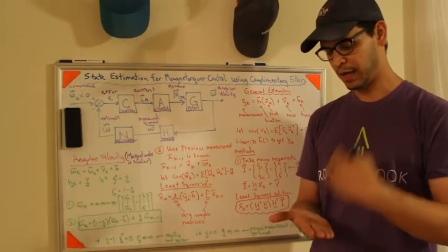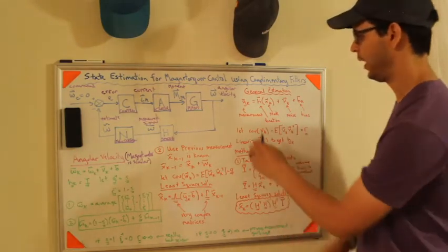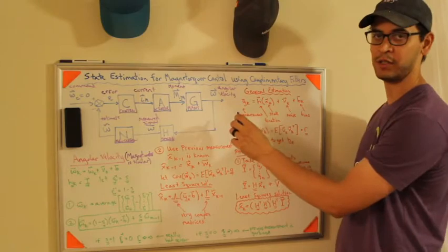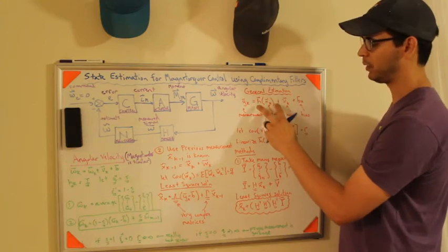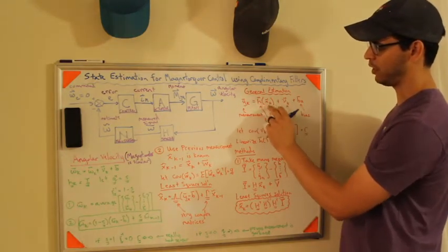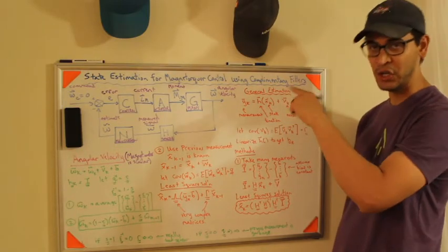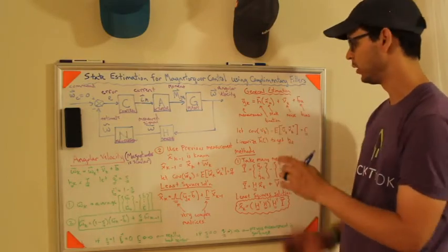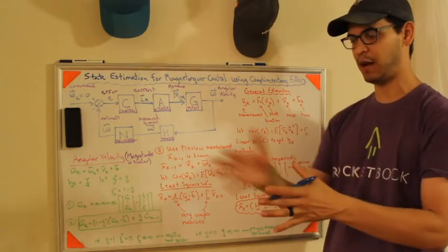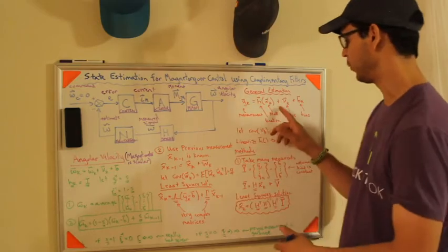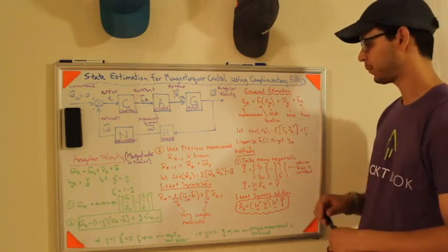Sensors are the same thing. Every fraction of a second, you're going to get a discrete measurement, and we call that y_k. The bar just denotes that it's the measurement. Now that y_k bar is going to, generally speaking, be some function h of x, the state, plus some noise, which we call nu, the Greek letter nu, n-u. It's not v, it's nu. And plus b_k, which is a bias. So there's going to be an offset, there's going to be a random noise, which we assume is Gaussian, and there might be some nonlinear function of x.